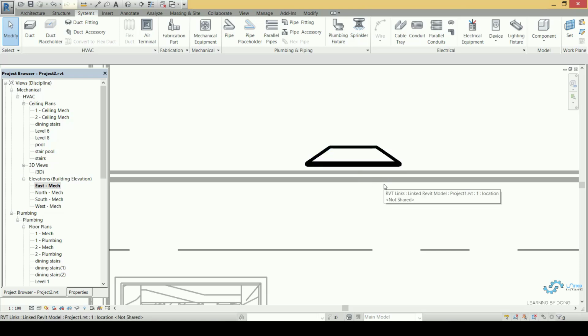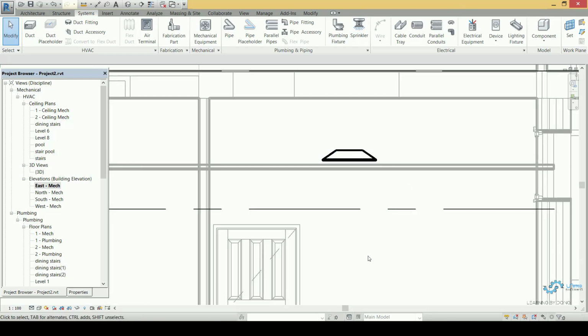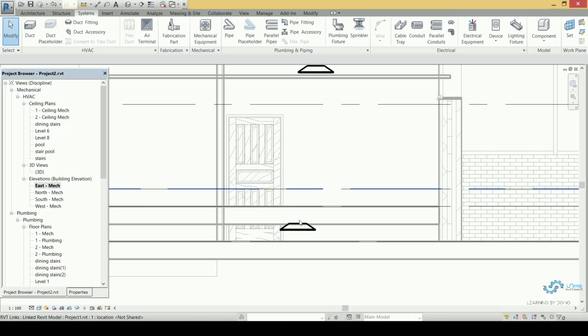But you know, we need the diffuser to be aligned sharply with the suspended ceiling surface, and to do so easily, we make the offset of the diffuser we have to be the same value or the same height of the suspended ceiling from the ground. So if we go down, we will find that this is the first diffuser which we have inserted.